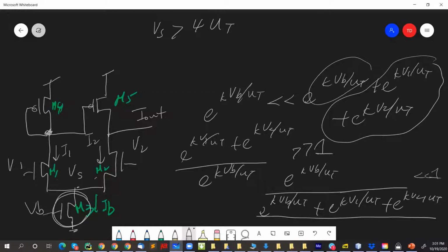Yeah, it was actually for the previous one when you were analyzing. Oh, I see. Okay. Yeah, you're right, it's for small signal. So it's saying that whenever there's a small change in delta V, how much does the current change? So then you can talk about GM, but for large signal, you cannot talk about GM.